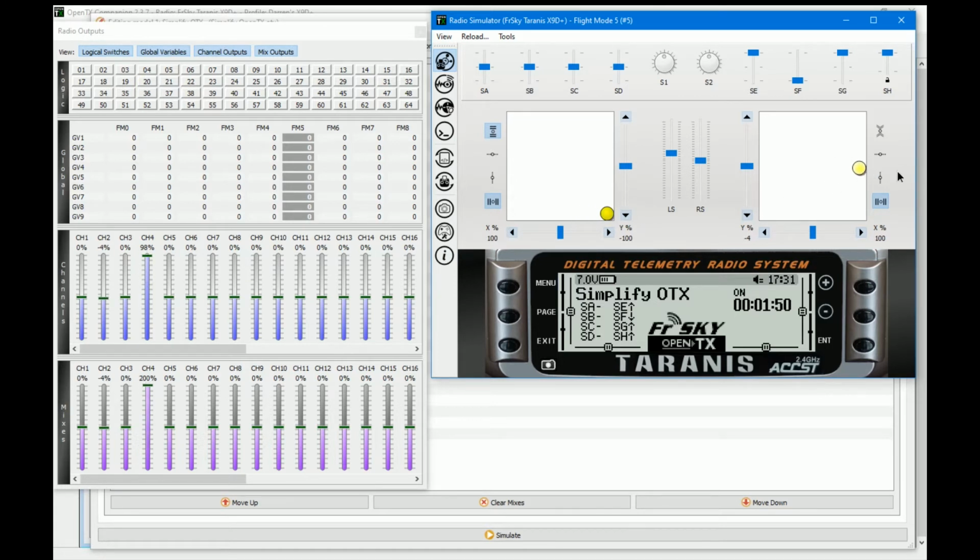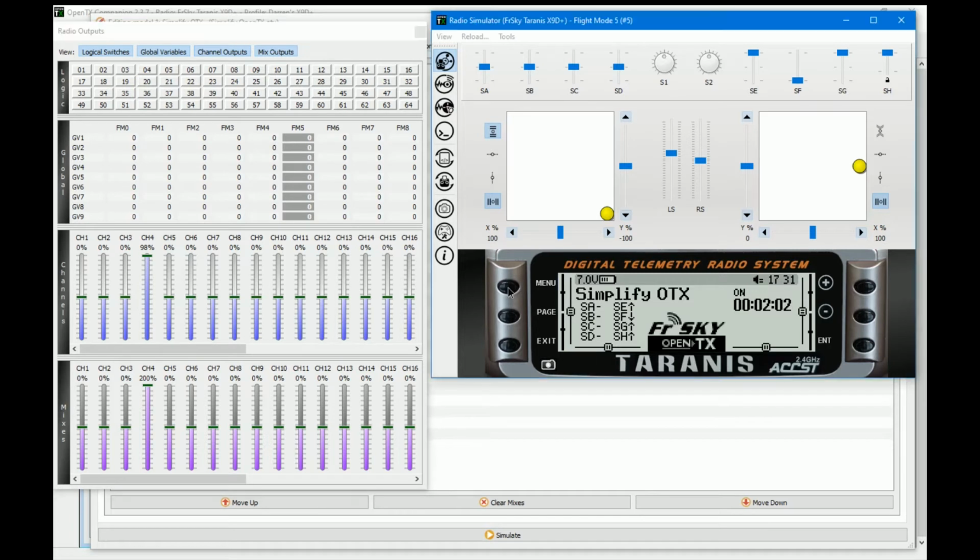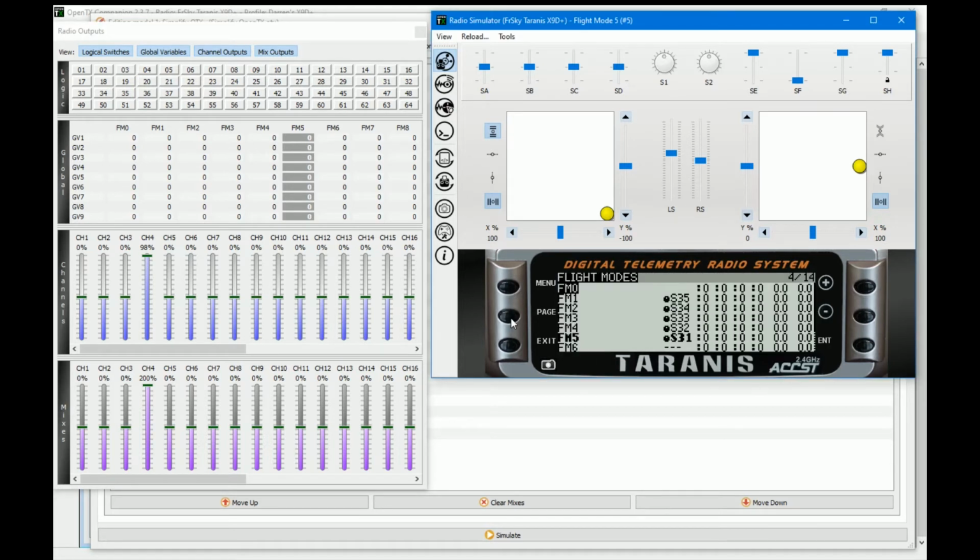So we put those both up to 100. You'll see that the output channel is only at 98 for some reason. It must be in the output settings somewhere. Let's have a look. So we go to the output screen. Maybe it's, yeah, it's got all this minus 97. That's for iNav, so that's why it's doing that. If I go down to rudder and reset, it's now 100%. So that's sorted that out. I'll go through and sort those out properly later.